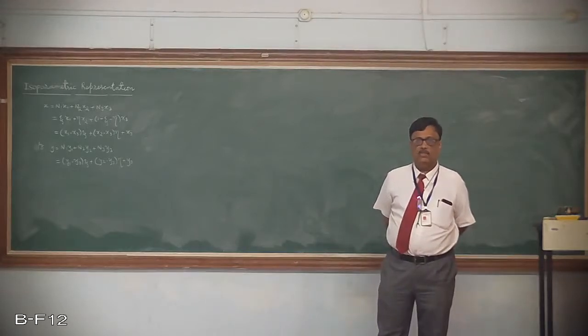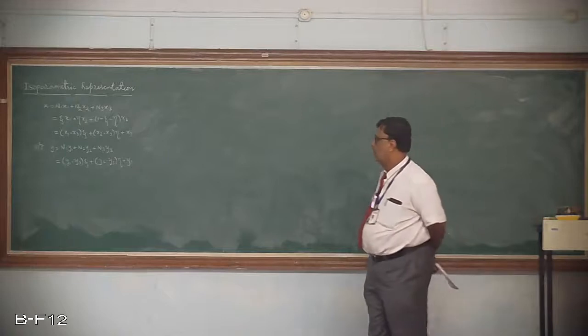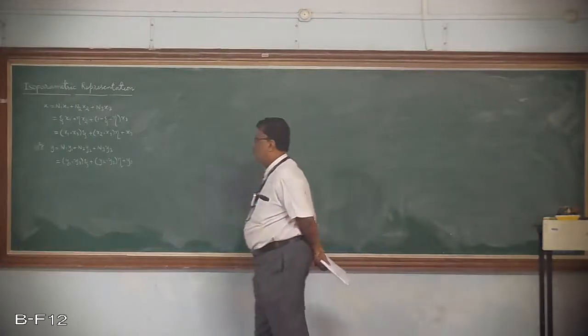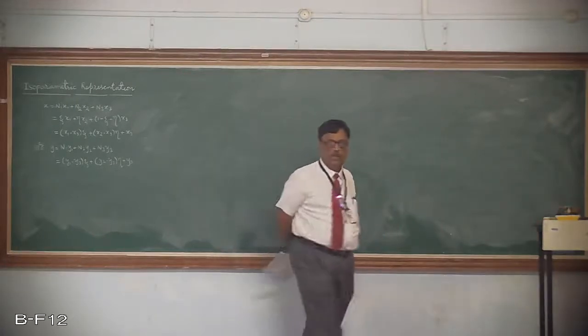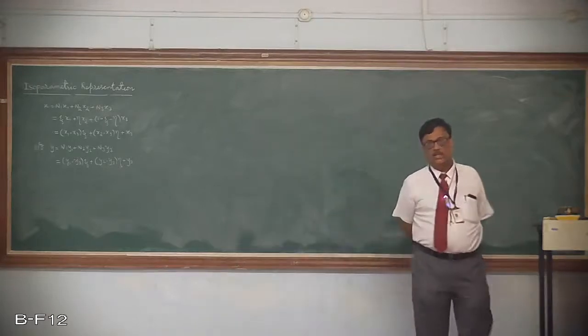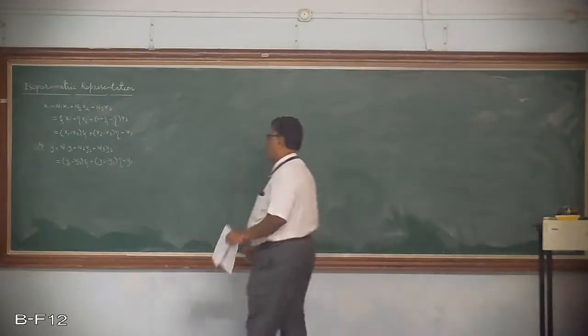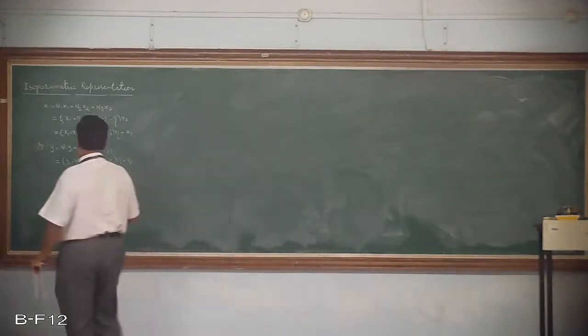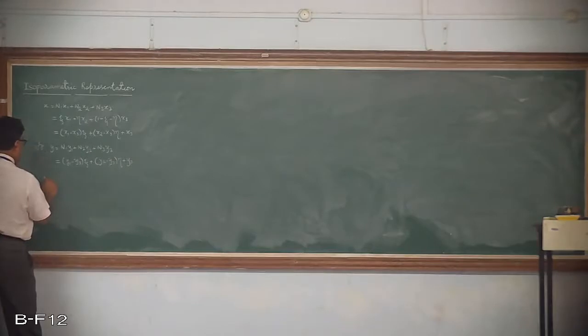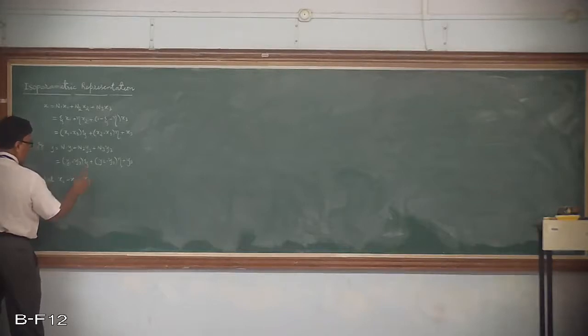You can derive the shape functions only once, and by using these shape functions, I can find out the coordinates of a given point if I know the coordinates of the other three nodes. Suppose we use a notation: xi minus xj, I will represent as xij. Or even if you want xj minus xi, I will call it xji. This is the convention I am using.